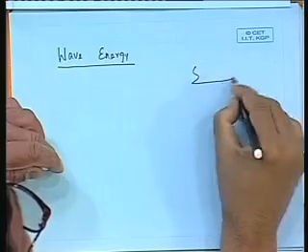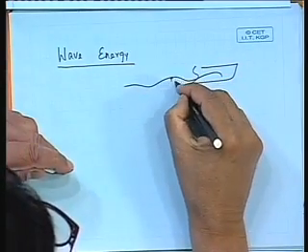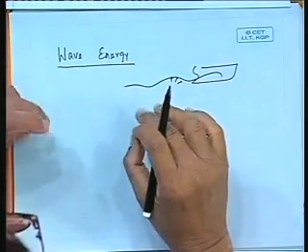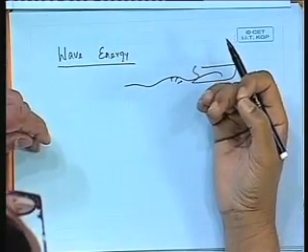The reason is that when the ship is moving, it creates waves. Now there were no waves there. Wave means something is moving. Something moving means there is energy, because without energy you cannot make it move, half mass v square. So somebody has supplied the energy. Who has supplied? The only thing around is the ship. So the ship has supplied. How did it supply? Energy is work done, force into distance. So there is a force that has been exerted to create that energy, which is making the waves. Therefore you need that extra thrust.